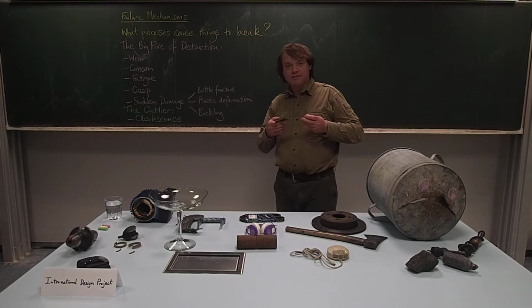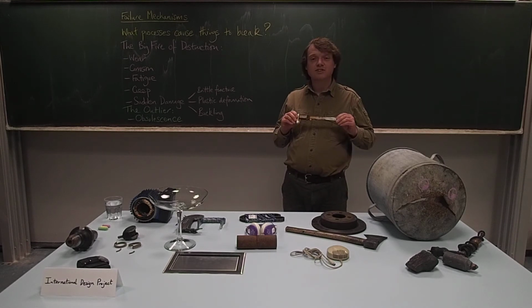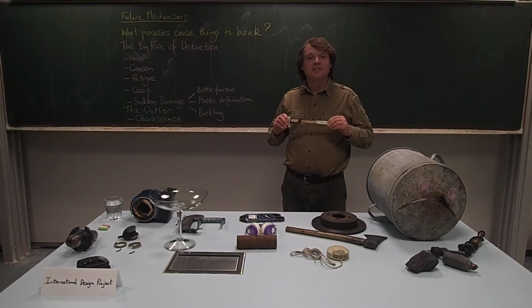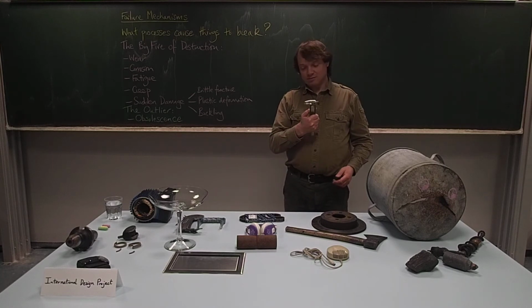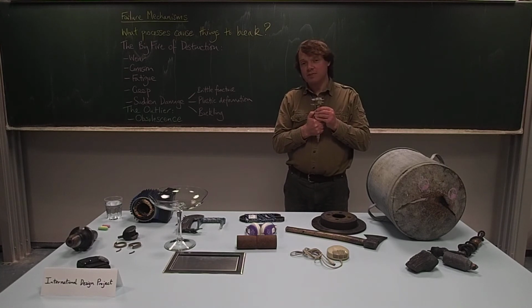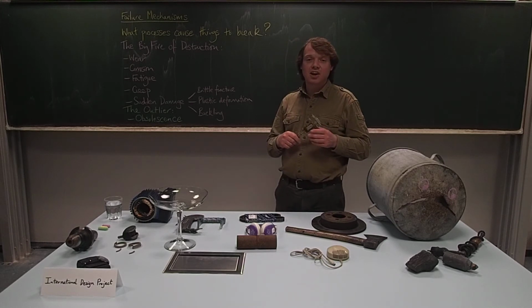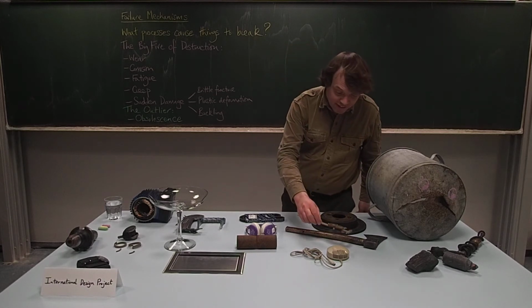So here's a pair of calipers, which are either made out of regular tool steel instead of stainless steel, or they've been left in a corrosive environment, and you can no longer open them, or you can barely open them, because the rust has expanded, because the iron oxide has a larger volume than the iron. Other things it could do,